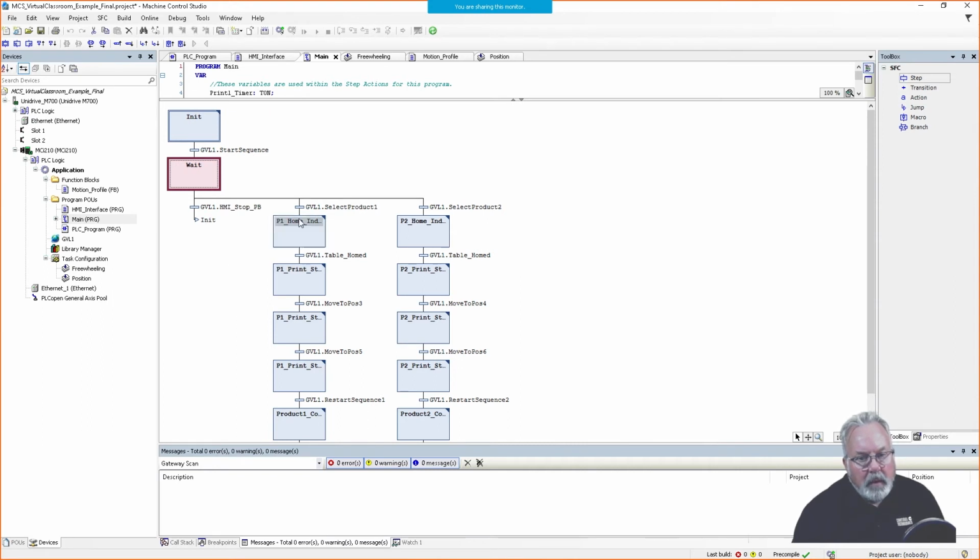It's probably better to look down here. There's a transition. So if I'm homing my motor, I can't get here unless that is true. So if something were to go wrong during operation, whatever that something is, and I were to go online, it's just going to hang right there on the step that's causing the problem.